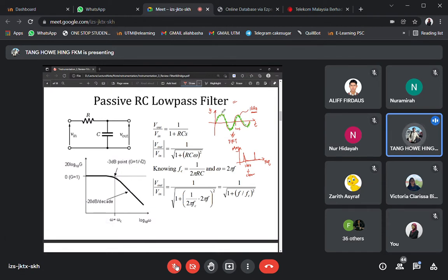So let's say this green color graph is essentially a combination of both 1 kilohertz and the 10 kilohertz noise. Okay, so that's why we have this 1 kilohertz. It is exactly the clean signal that we want to extract, and this 10 kilohertz is the noise that we want to get rid of. Okay, so if we perform the FFT, for the green line,